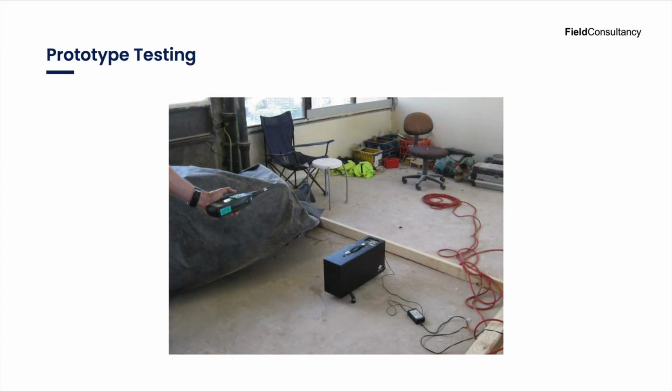We undertook some prototype testing of all the different tile and wood floor build-ups, and we first of all started by doing a prototype test on the bare concrete floor alone, which theoretically should give us our worst case scenario for the impact sound pressure level in the apartment below. What we used was a standard tapping machine, which consisted of a series of weighted steel hammers that randomly hit the floor surface to produce an impact sound pressure level we could measure in the apartment below.